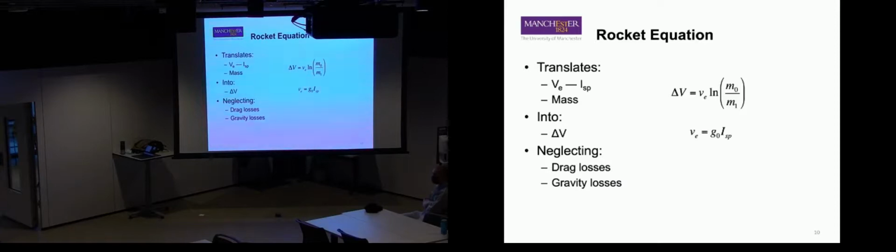And what that means is all of that ancillary structure, tanks, rocket engine, all of that is just dead weight lugging around for most of the flight. Now, it's not dead weight in the sense it serves a purpose, but once that tank is almost empty, all of that structure above it that's not containing the fuel, we're lugging dead weight around. The same thing with an aircraft, by the way. We see that natural log, m_0 over m_1, in the Breguet range equation, which you'll become much more familiar with next year in design. So this is one of those exponential behaviors. It's exponential with ISP and then scales linearly with that. So we want to get rid of that.